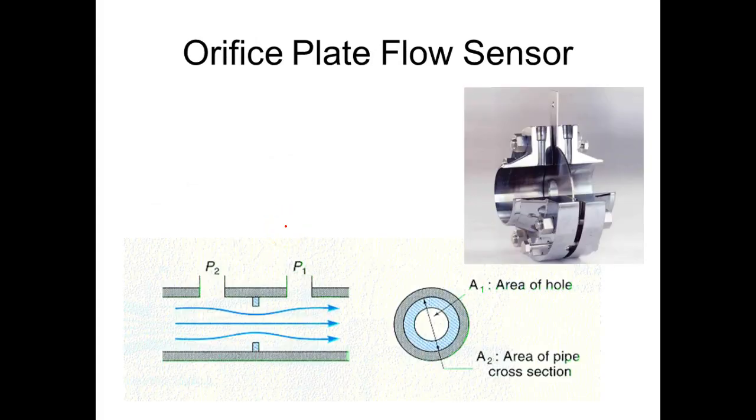So this is the orifice. We use this a lot because one thing, it has really no moving parts. But what we do is we force the fluid through an orifice. And the size of the orifice, of course, it speeds up right here, right? You understand? And then it comes over here and it creates a pressure differential.